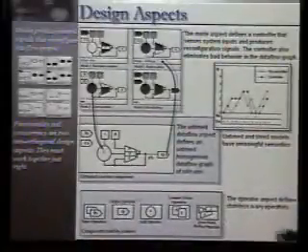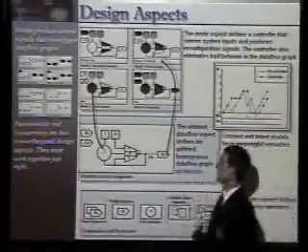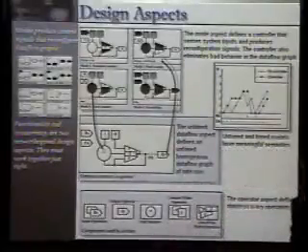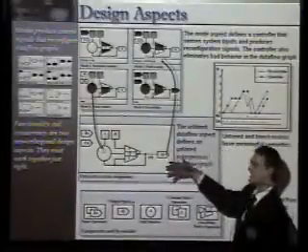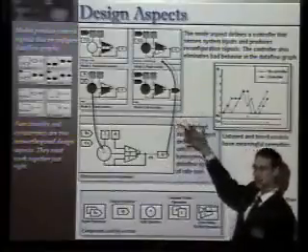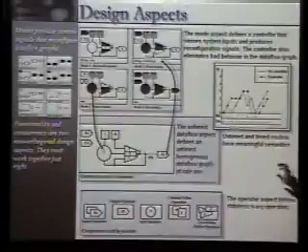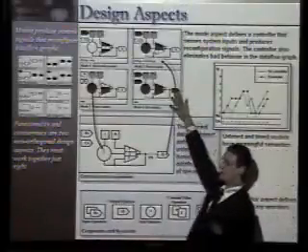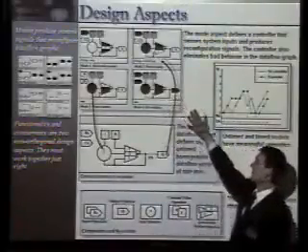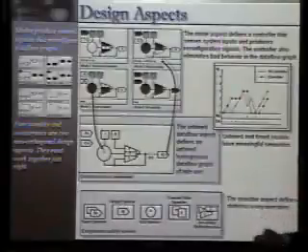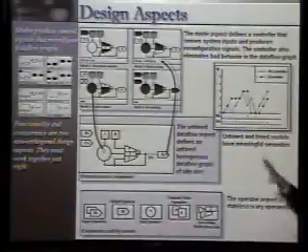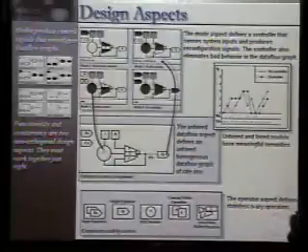Okay? So you can see it's sort of like in classical digital design. You design a data path, and you design a controller on top of it. But in this partitioning, each one of these has a very precise semantics. Synchronous data flow graph and a set of modes. There's very precise semantics about when you apply a mode and the sorts of conditions it can have. And it allows you to reconstruct a synchronous model in a model-based way by partitioning it this way.